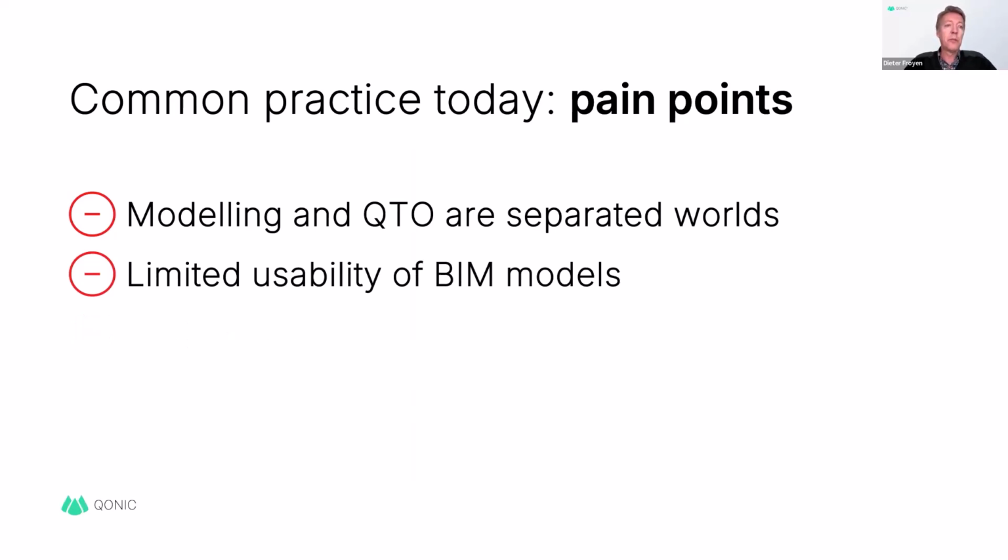Linked to that, you can have a limited usability of BIM models. Quantity takeoff is only one of the many workflows you have in a BIM process on a BIM project. And so not all the time the BIM model is suited for a reliable quantity takeoff. You can, for example, see that the geometry is overlapping, that there is not enough detail in the BIM model, or that data is missing or of bad quality. So that this limits the usability of a quantity takeoff.